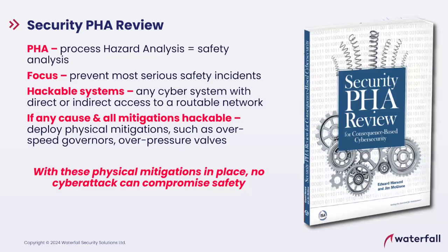And then there's a column for all of the trigger events that could cause the boiler to explode. An earthquake crimping the output valve, and now the steam cannot escape, and the boiler overpressurizes. And then there is a column for all of the mitigations that are in place to prevent the boiler exploding. There's the overpressure relief valve. There's alarms that come up on the HMI, and the operator has been trained when they see this alarm to turn off the fuel flow to the furnace and shut things down. There's safety instrumented systems that can shut down the furnace. So these are all mitigations.